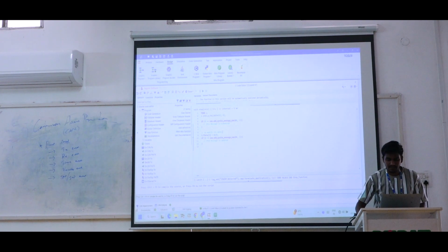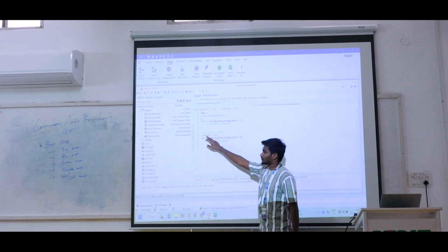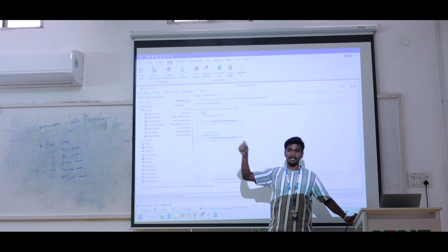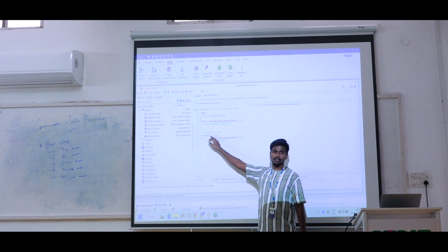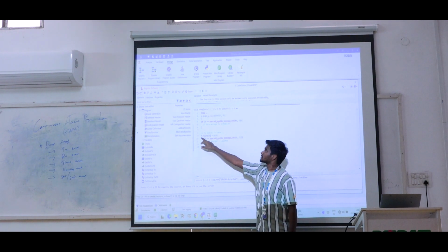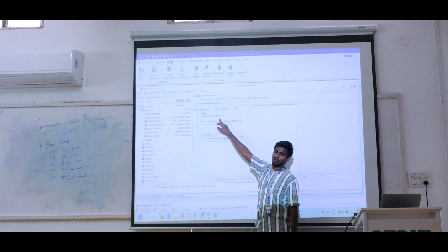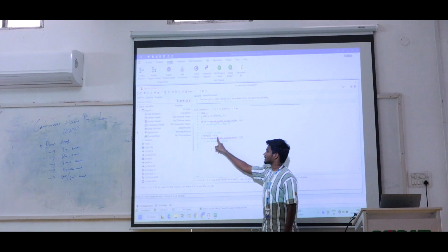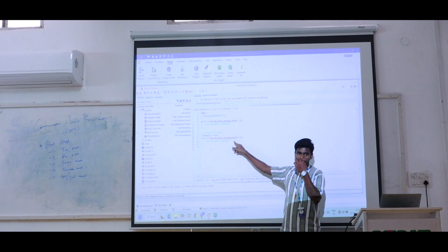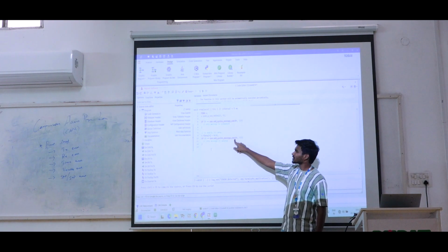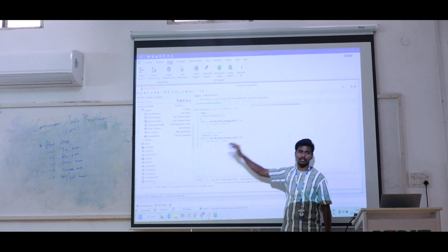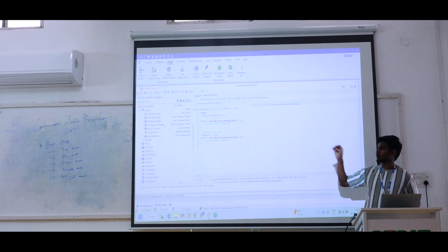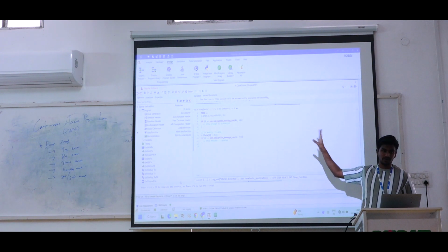This line is where we give the data. The data of 0 means, just like in our CAN program where we use CAN data of 0, CAN data of 1, the first byte, second byte, third byte. The key is ID number 123 with DLC of 8. You can take the first byte value, which is 0x34. After sending this value, using the same line, we send the modified data for ID number 123 again, with a period of 5 ms. These are inbuilt codes that come with it; we just modify them, and that is enough.